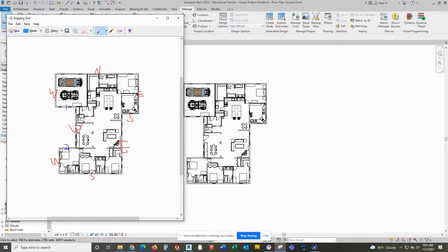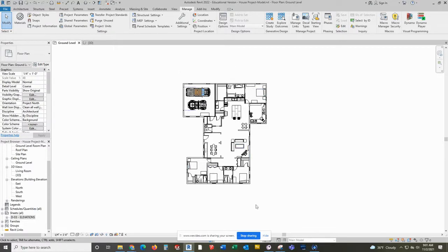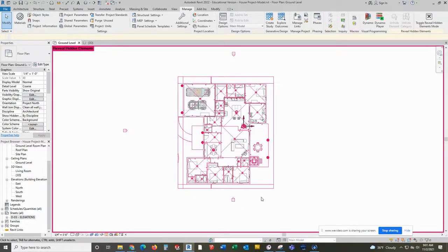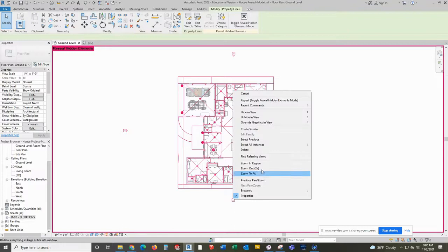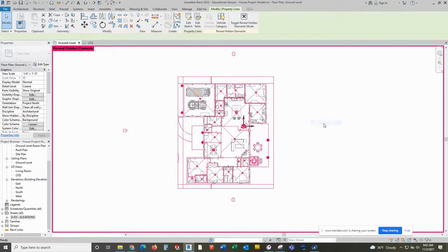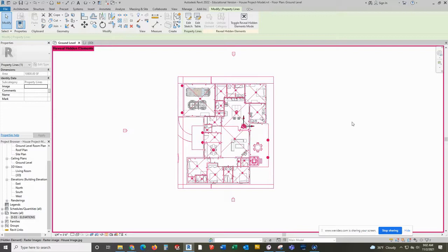So for me, I have my regular elevations. It's going to give me the vast majority of what I need. And I have 2 walls that I'm going to have to set up a special elevation for. So right now, in this view, I'm going to show my hidden elements, which there's going to be a bunch from site plans and everything else. And as you can see, I have my elevation markers. I'm going to right click on my elevation markers, Unhide in View, and unhide that category, so I see all of my elevation markers.